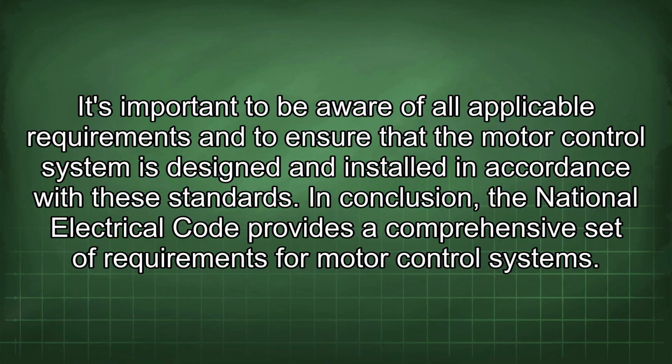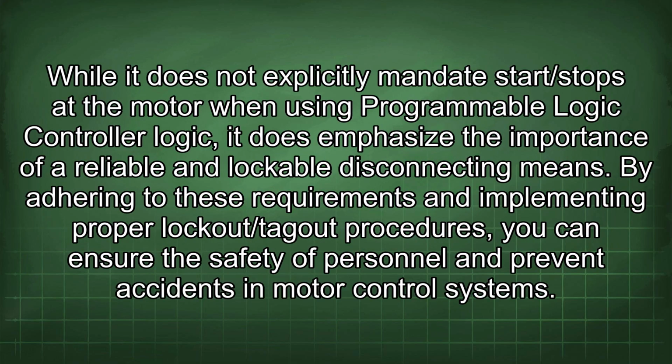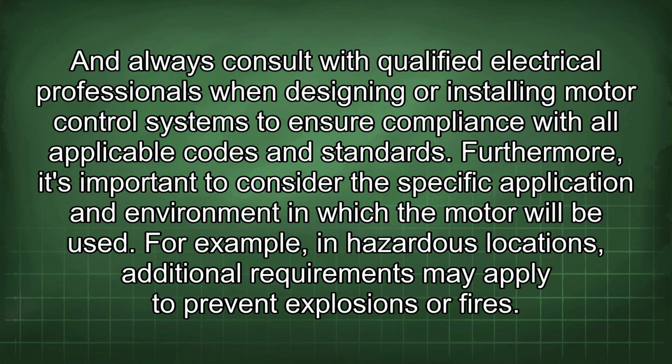In conclusion, the National Electrical Code provides a comprehensive set of requirements for motor control systems. While it does not explicitly mandate start/stops at the motor when using Programmable Logic Controller logic, it does emphasize the importance of a reliable and lockable disconnecting means. By adhering to these requirements and implementing proper lockout/tagout procedures, you can ensure the safety of personnel and prevent accidents in motor control systems. And always consult with qualified electrical professionals when designing or installing motor control systems to ensure compliance with all applicable codes and standards.